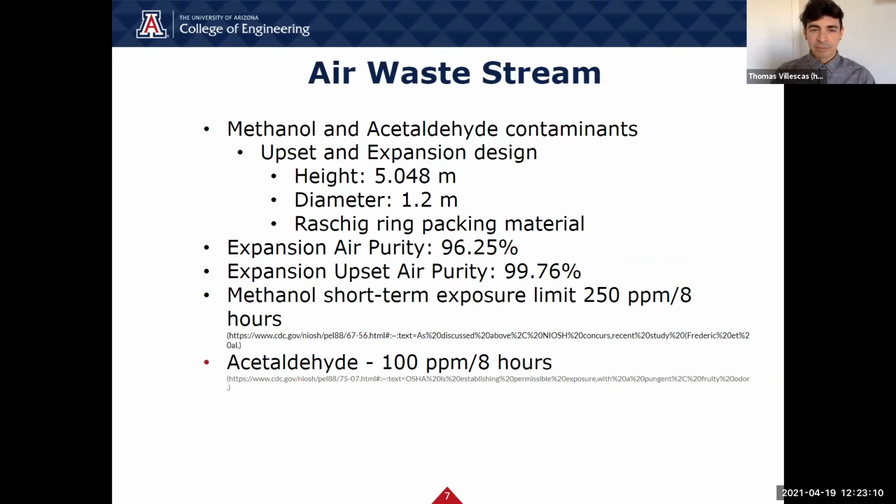The purity of air that will be sent to the atmosphere was determined to be 96.25% under normal operating conditions and 99.76% purity for the EPSA conditions. This allows for the air to remain under the short-term exposure limits of both acetaldehyde and methanol set by OSHA and the CDC. All spent water containing the absorbed contaminants will then be sent downstream to the biopond for degradation.